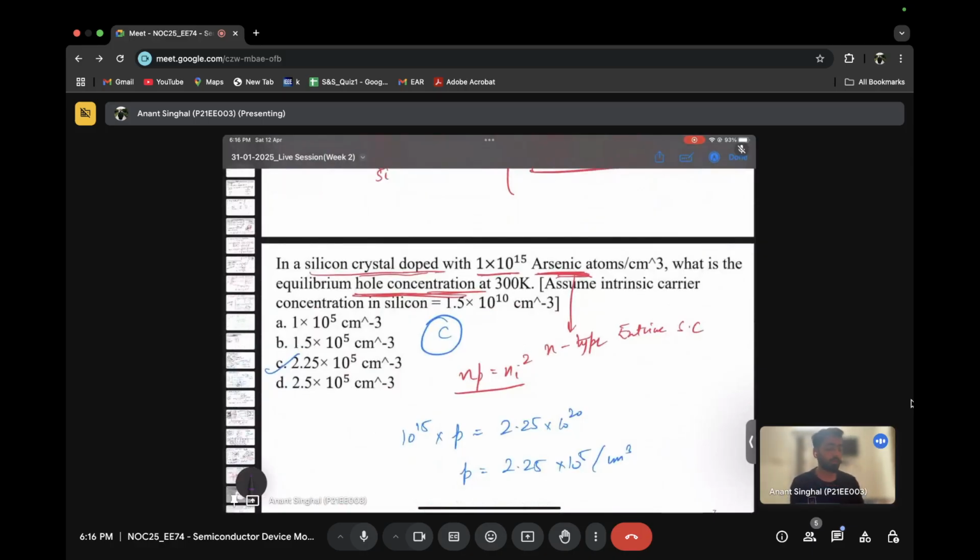Here come all the very basic problems. You know that for an ideal semiconductor, that is, an intrinsic semiconductor, at equilibrium the number of holes should equal the number of electrons to make it neutral. Again, this is the mass action law. This is a very important law which only holds at equilibrium, first of all. These are some straightforward problems.